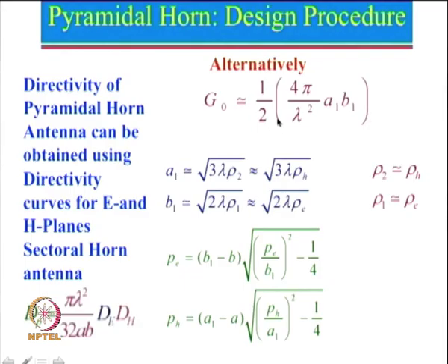If you look into that, this means that the efficiency of this particular antenna is only 50%, and I actually want to mention that all those optimum dimensions which we had seen really give rise to an efficiency of only about 50%. But I also want to mention that some books do take, instead of 0.5, 0.6 also. So, some books take this 60% efficiency, some take 50% efficiency, but we will show you much later how to get even better efficiency. But right now I will go with this textbook approach, and we will see how things can be simplified and designed.